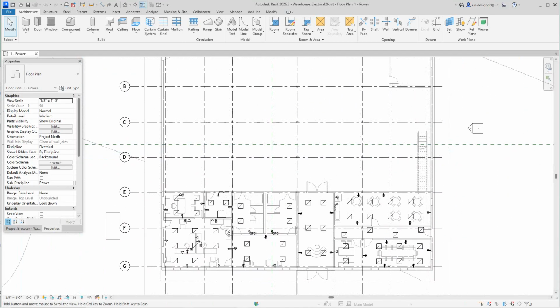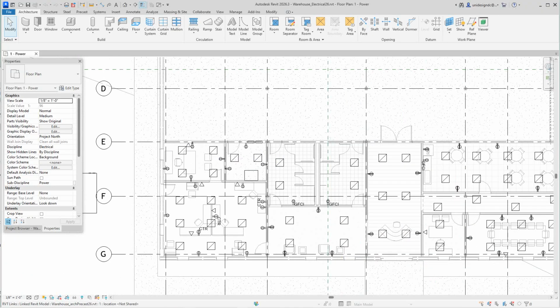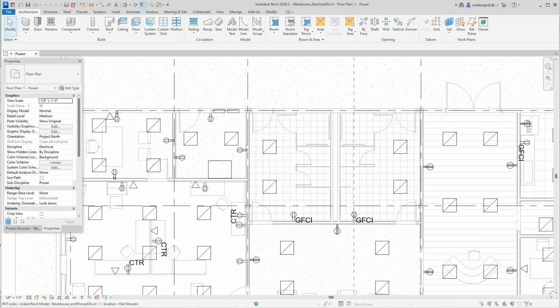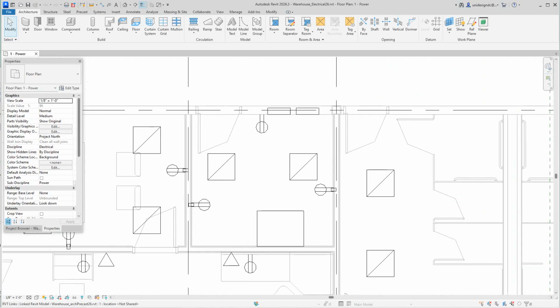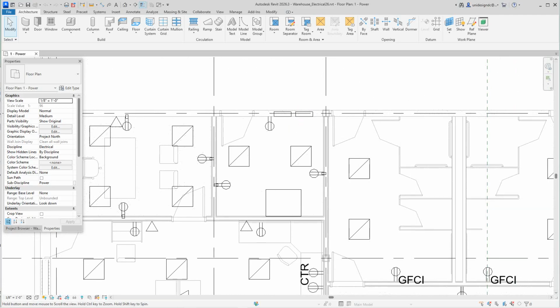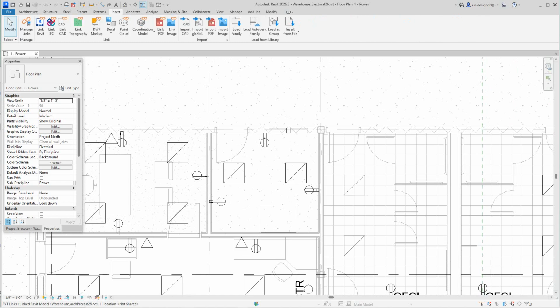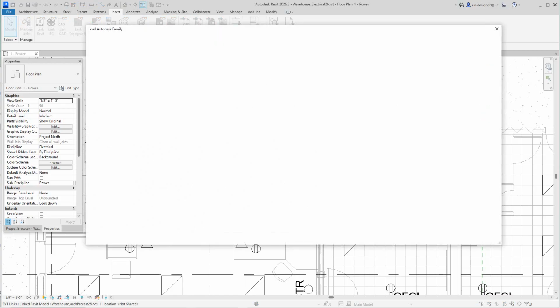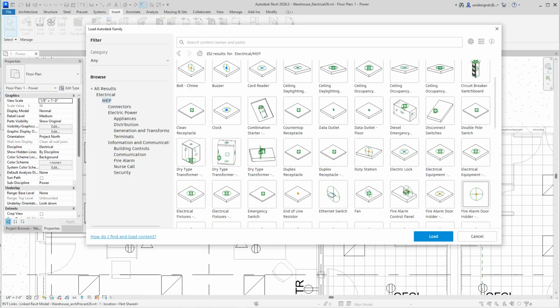We're in our electrical model, and I've laid out some components, and as you can see, we've got the background going on here from our architectural, and we're showing several things here. So over here, I'm showing the electrical lighting and appliance panel, and to load those in, you might want to go to your Insert tab here and go to Load Autodesk Family from the cloud, and here you'll find all of your electrical MEP components we're going to use here. So there's all of your components,